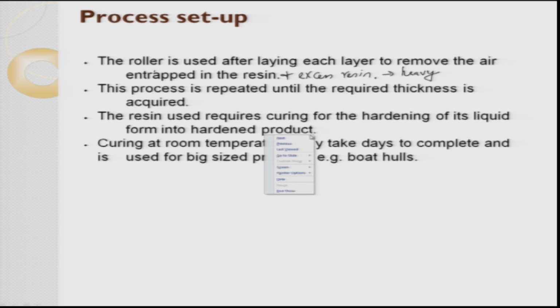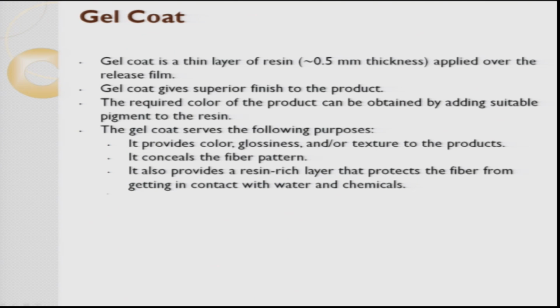So, that is what I said, all the ingredients. The curing at room temperature. So, the curing can happen both at RT as well as at elevated temperature depending upon your requirement. When it is a large size product, it is always done at room temperature only. And here you can use epoxy resin, you can use polyester resin depending upon your requirement.